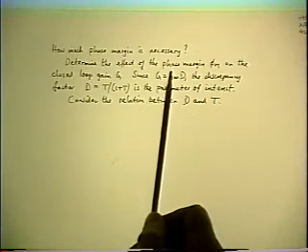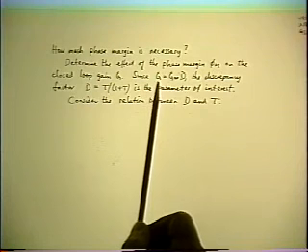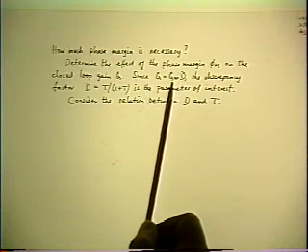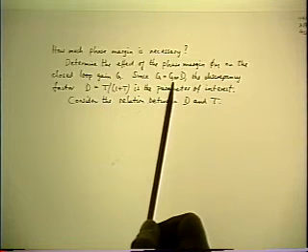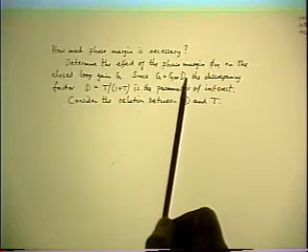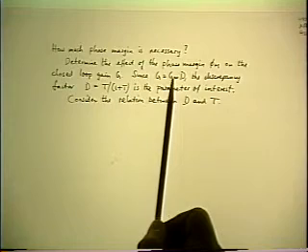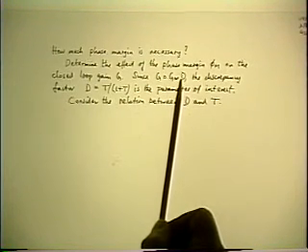So the most important property of the feedback system is its closed loop gain G, which is G infinity times D. Now G infinity is designed in right away according to the specification, and the feedback path is designed to do that. What's important is how close is G to the G infinity. And that's what the discrepancy factor is about.